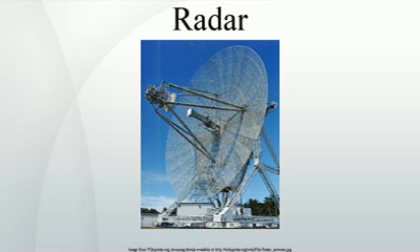Clutter. Clutter refers to radio frequency, RF, echoes returned from targets which are uninteresting to the radar operators. Such targets include natural objects such as ground, sea, precipitation, such as rain, snow or hail, sandstorms, animals, especially birds, atmospheric turbulence, and other atmospheric effects, such as ionosphere reflections, meteor trails, and three-body scatter spike. Clutter may also be returned from man-made objects such as buildings and, intentionally, by radar countermeasures such as chaff.